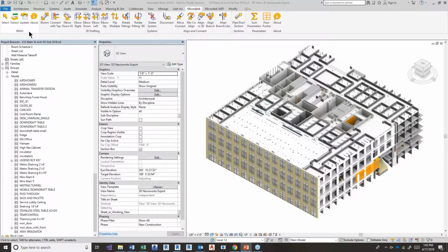And if I'm imagining round-tripping information to and from Excel, the first and easy example of something that I might want to do is correct a common issue with Revit models, and that is duplicate mark values. When we've got multiple users working together in a project, drafting the same type of element, oftentimes Revit will inadvertently assign 2 equal mark values to 2 different elements, which we know generates warnings that we prefer to clean out for housekeeping. So we can use the BIMrx tool to export information about our elements to Excel, use Excel's ability to auto-increment numbers, and then round-trip the mark values back in so that we know there are no duplicate values.